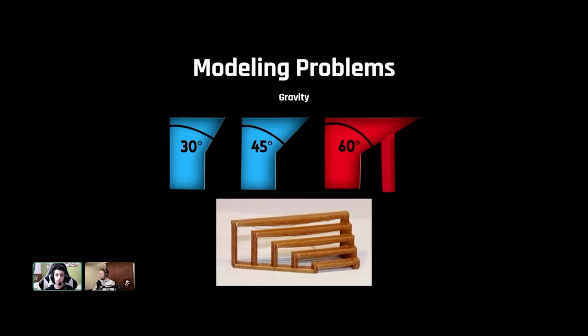However, there are some exceptions to this 45-degree rule. If there are two walls and the printer is just making a roof, if you will, between them, depending on how far away the walls are, the printer may not need supports, as shown in the bottom picture. The farther away the walls are, the more the plastic droops down. A good 3D model has to take these issues into consideration without interfering with the final result.